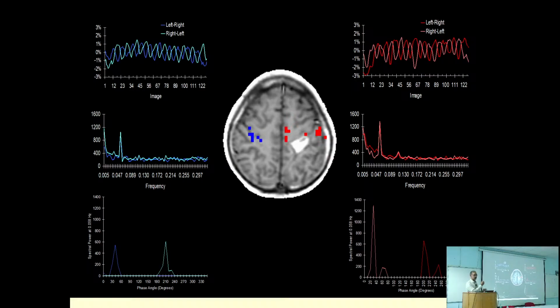The correlation will be a little less because it has been shifted. However, if you have an apple and then an orange, the correlation will also be less. Just because it is less, it doesn't mean there is no effect, right? So one has to be careful about the phase information. And by doing frequency analysis, you're looking at whether it contains the same frequency.